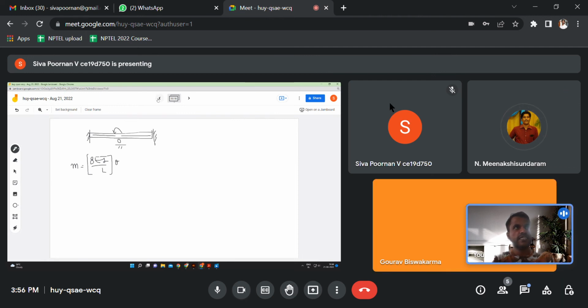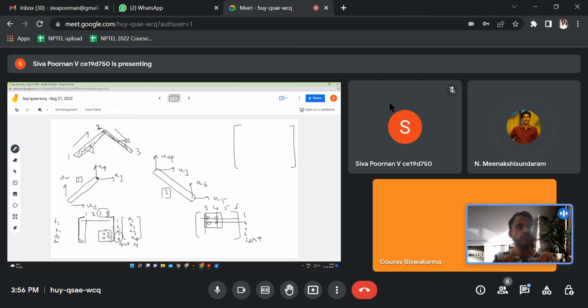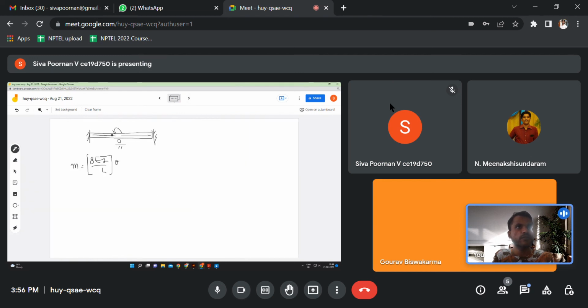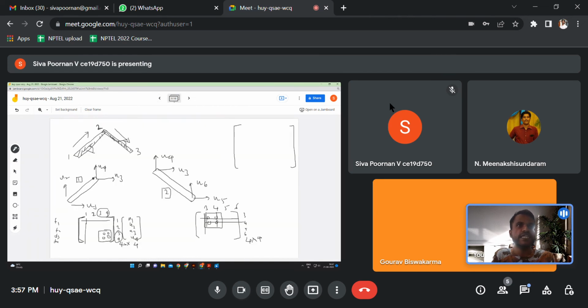And that's the same thing that's happening here. If you see both these points, they have the same displacements. The rotation is going to be the same, the moment is going to distribute, right? And that's what we saw, that if you have two springs in parallel and you apply a force F, it will go as F1 and F2, and you'll have the displacements be the same. Both will have a delta displacement, right? And the same thing is happening at this point. That is why the stiffness from one member at the same point should be added to the stiffness of another member, because both the points are going to be in parallel when you attach them.